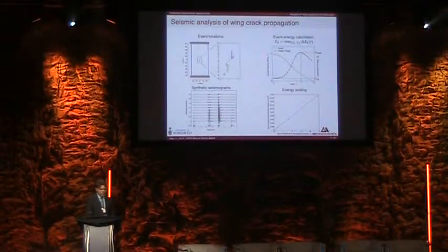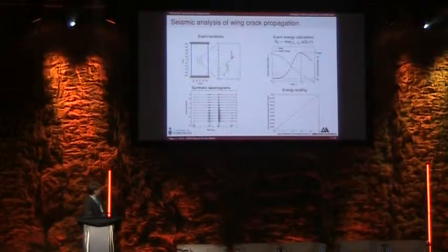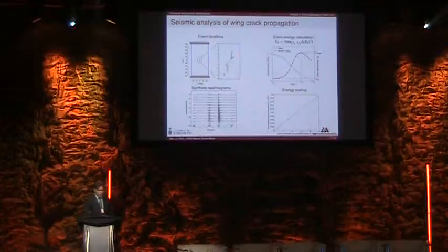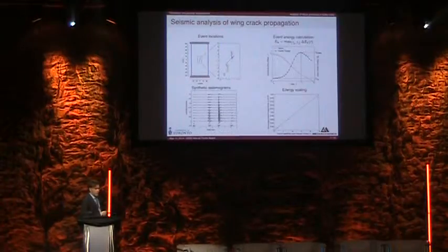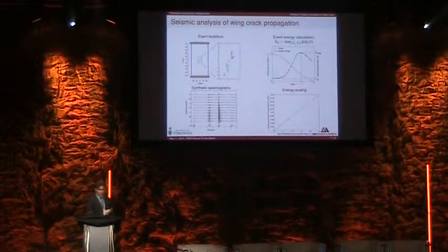As I said, the first part of the research was mainly focused on further validating the code in terms of can we reproduce brittle failure in rock correctly. And we'll look into can we capture the release of seismic energy during the fracture propagation process. This is just a simple example: a simulation of a compression test, no confinement, and there is a pre-existing discontinuity at the center. We compress that, and we can simulate the wing cracking, so tensile cracks developing from the flaw.